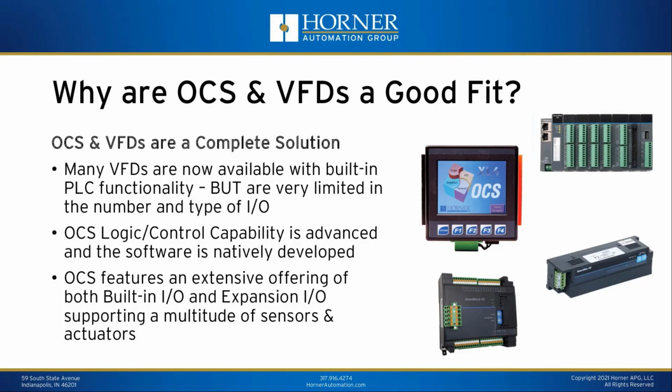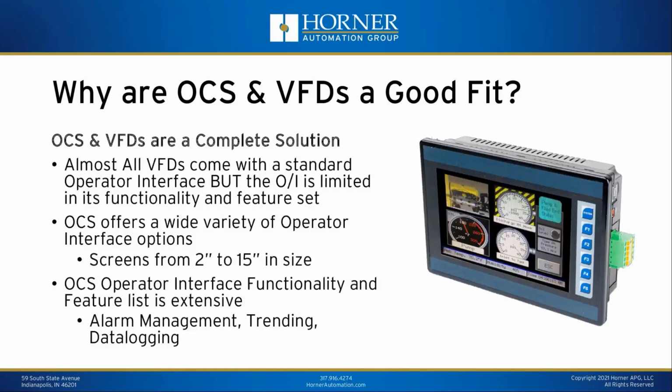So having a wide variety of I/O either built into the OCS all-in-one controller, or able to be added through expansion, is certainly a big strength of the OCS. There are a lot of sensors that you typically wouldn't find interfacing with a variable frequency drive that will interface very well in the case of an OCS. For instance, RTDs, thermocouples, those sorts of temperature sensors are a strength for the OCS for sure, and not something you typically would connect directly to a variable frequency drive.